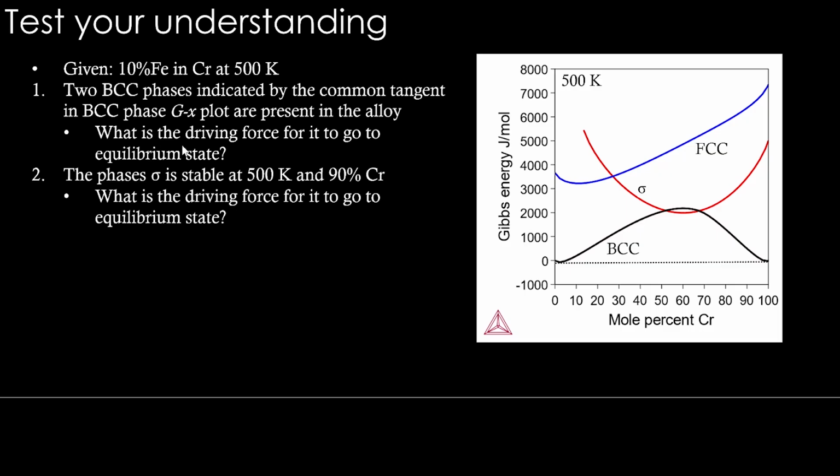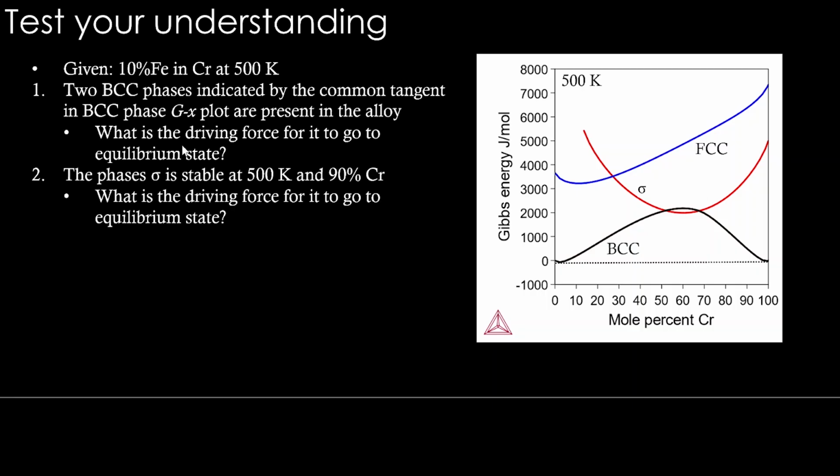Why this question is asked is because if you want to identify what is an equilibrium phase, there is a way to calculate for any phase what the driving force is to go to equilibrium state. If the driving force for a phase comes to be 0, in CALPHAD software tools you will see that it means it is the stable phase. So that is how you identify stable phases in CALPHAD tools.